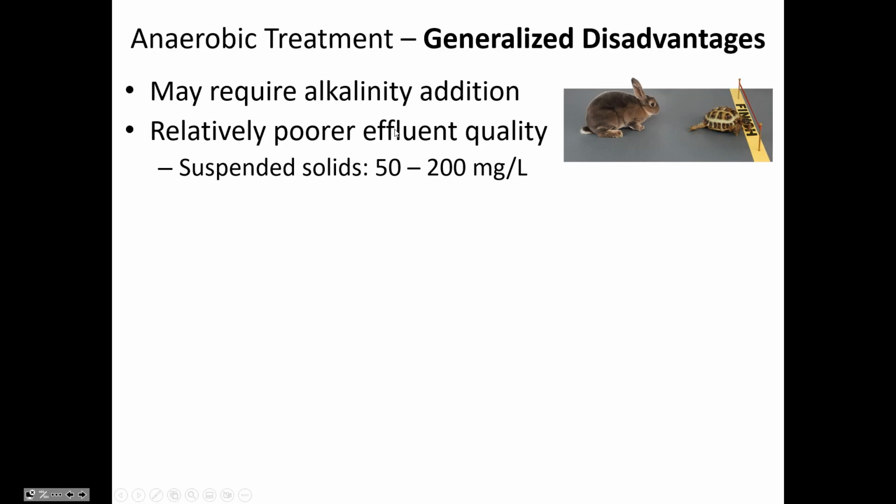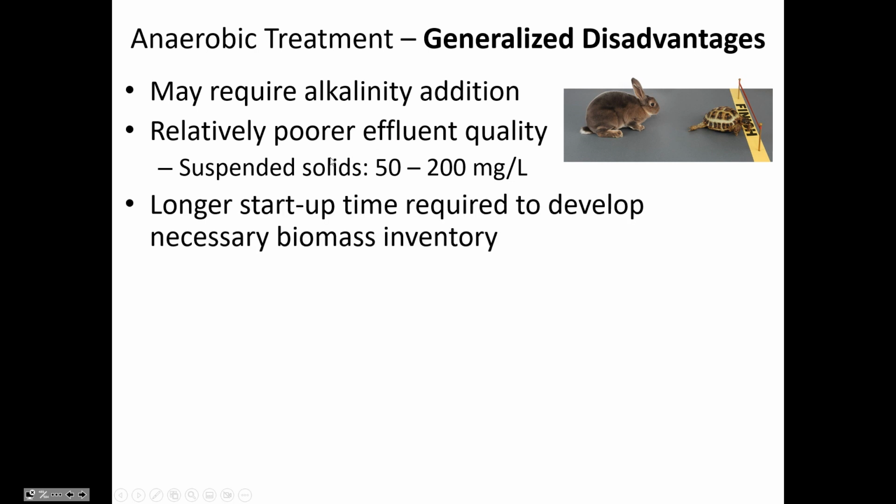The suspended solids are higher than they would be in aerobic treatment, and because it's so slow, there's a long startup time where if you have some sort of a shock or a toxic come through the system and wipe out all of the microbes that are living in a sludge digester, it can take months to reach equilibrium again.